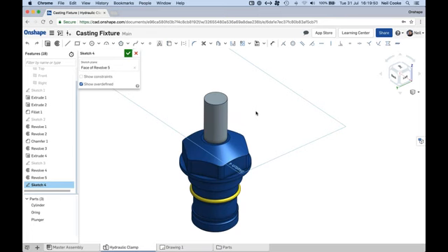Now, what we're doing right now, and I'm going to come back to this in a moment, is we're building a brand new part inside something called a Part Studio. Part Studio is unique in the CAD world, because it enables you to build related parts together, much in the way that you do an in-context design in an assembly in, say, SolidWorks or Creo. But you're not making file references across files, which can be a little bit flaky when it comes to references updating and predictability when you're making changes. So these are multiple parts built within one single part environment.